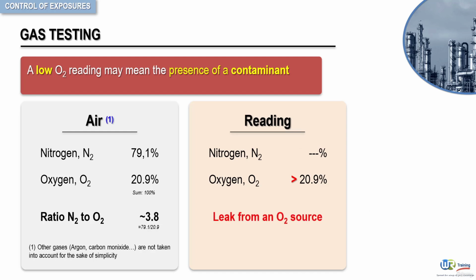In all cases, for your own safety, always make sure all areas of the work are gas tested and visually inspected. And remember, some vapors are heavier than air and tend to settle in low places, particularly in confined spaces. There will be more about this further ahead.